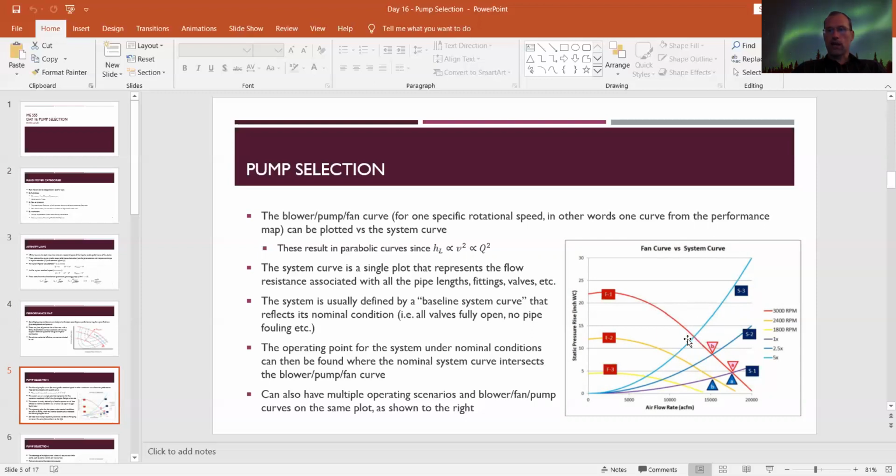Where the system curve and pump curve meet, this intersection is the operating point. That's what's going to happen using that pump with that diameter to get my water through this particular system. I'm going to end up with a flow rate of whatever this value is, and a certain head loss or pressure drop of whatever that value is over there. That's how I find my operating point.